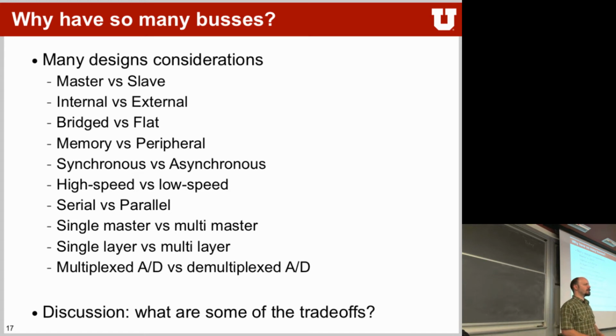All right, so what are some of the trade-offs that we have to make in bus architectures? Why do we have that many different buses? So let's go first to the internal versus external buses. What are trade-offs that we have to play? If it's external, you can access it from outside with a different controller, versus if it's internal, you can't just have any other slaves out there. Okay, so internal buses usually are permanently hooked up to something. It's not an extendable bus, correct? Yeah. What else? What's a huge difference?